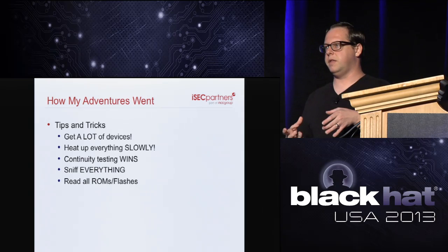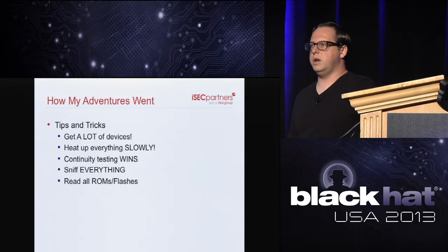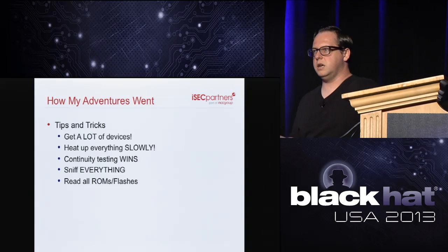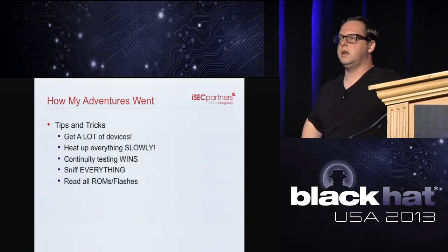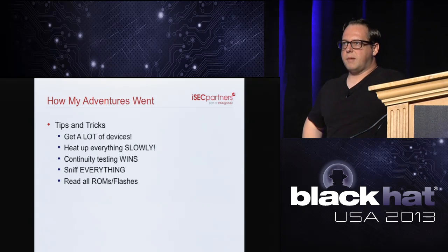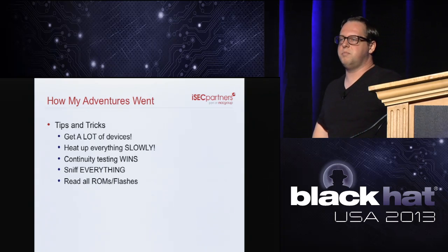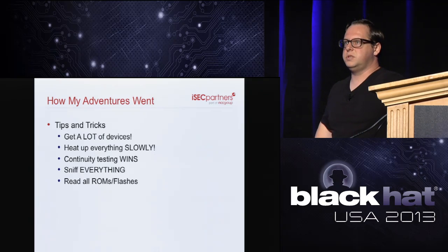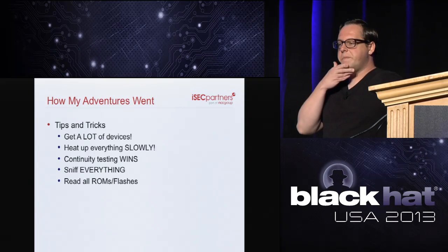So that's all metal that we're going to need to heat up to a correct temperature. Once you're around 180 to 190, then you can crank up your heat gun to around 220 to 250 and do some desoldering. I actually wasn't able to pull the chips off until I got up to around 300 degrees Celsius. Some of the EEs out there might be like, oh, that's awfully high, you're going to damage the chip. But I was successfully able to desolder them at that temperature and connect them in.